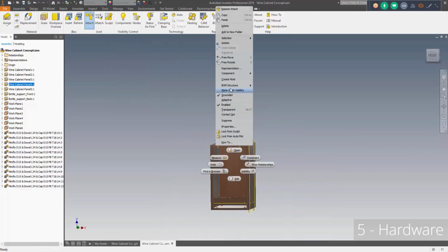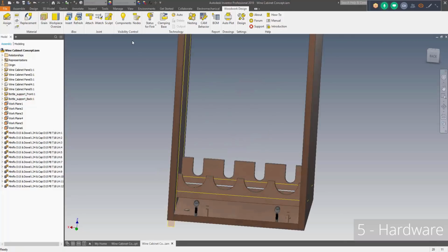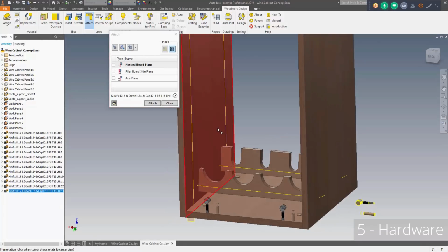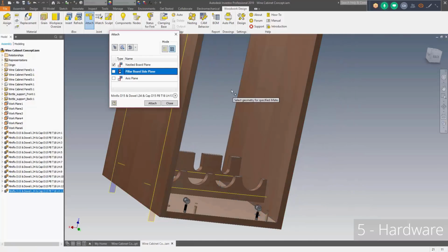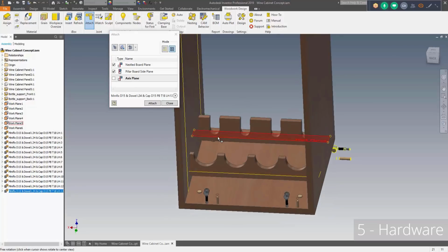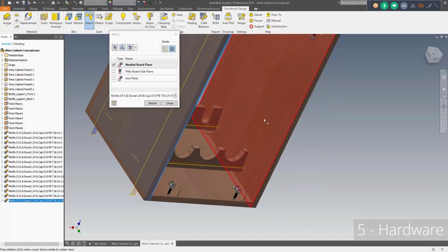Basically, that's what we have so far. We have all the components in place, but there is something still missing. We need to fix our supports. So we'll use the same idea here. We will try to fit this support inside of our assembly. Later we will see if it works for us, or maybe some changes will be needed. So we're trying to pick a reference geometry and say that we want to attach this minifix. And lastly, for the back support, the same procedure should be repeated.